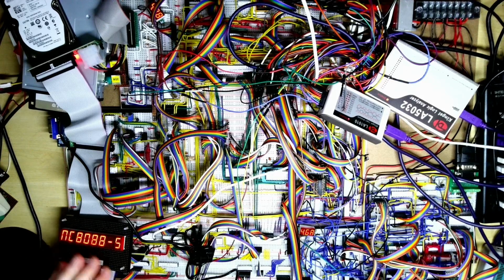So in fact the way I've configured this is with the monitor I can actually inspect memory, run test programs and things like that before I try and load up the BIOS and load up MS-DOS, etc. And then all I do is press B on the keypad there to actually boot the BIOS. And down the bottom here, this is parallel interface and a serial port.